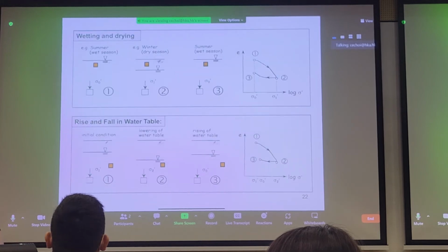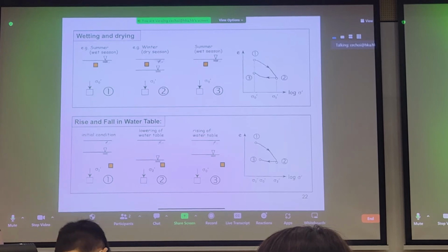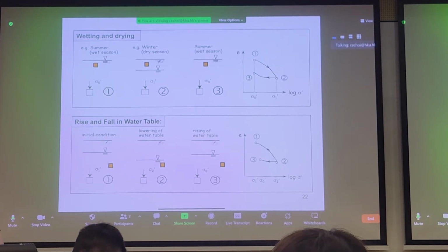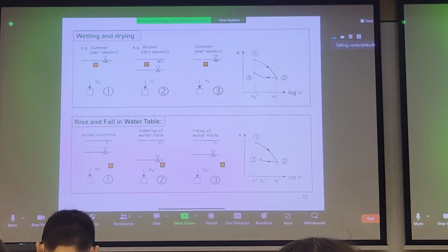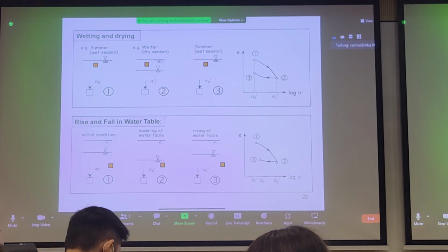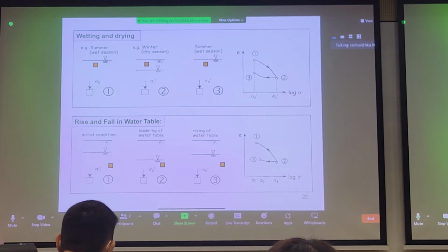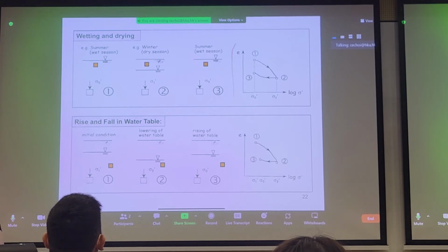Now, alternatively, you can also have what we call climate loading on the soil as a natural process. Now, there is a caveat though. We have to assume that this loading is somewhat rapid and it does cause consolidation. If it doesn't cause consolidation, you're not going to get any volume change. And this graph is not going to make sense.